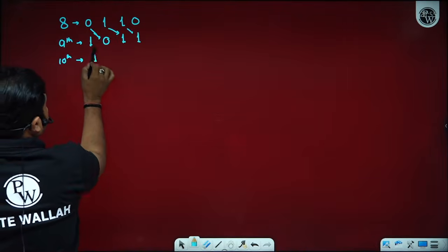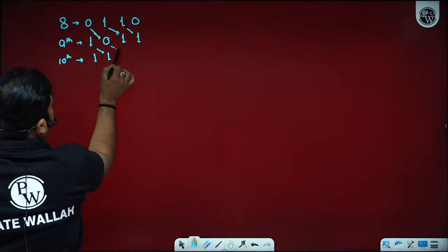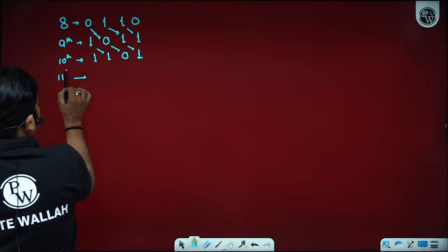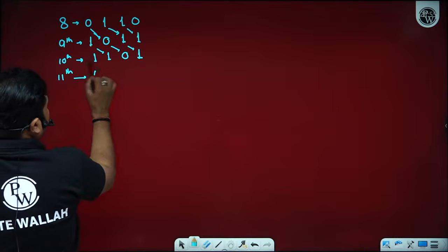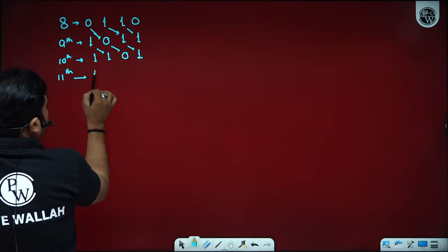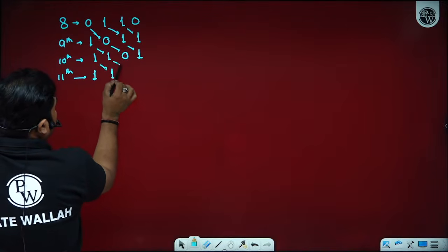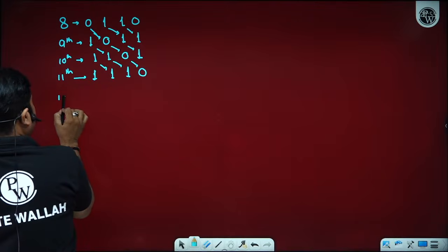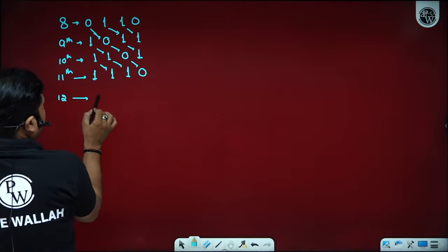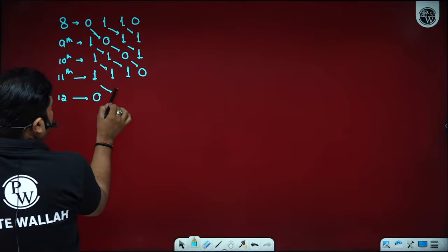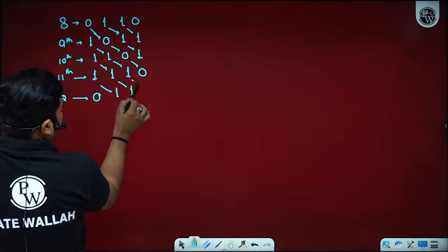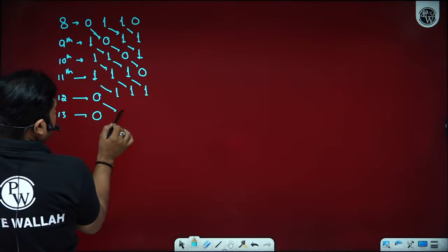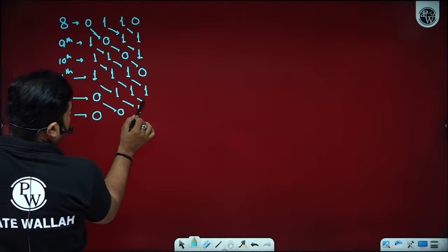Sir, 1, 1, 0, 1. On the 11th clock pulse, what do we get? 1, 1, 1, 1 will become 1, 1, 1, 0. On the 12th clock pulse, what do we get? 0, 1, 1, 1. On the 13th clock pulse, we get 0, 0, 1, 1.